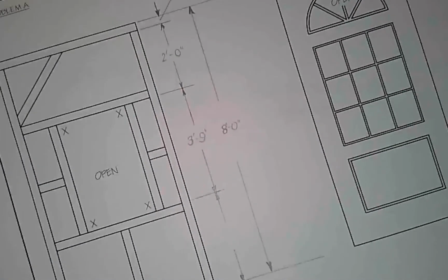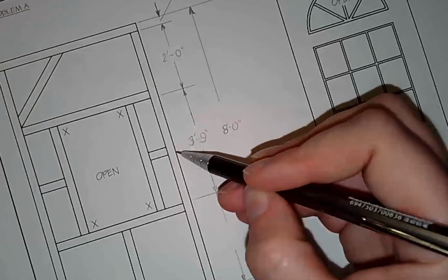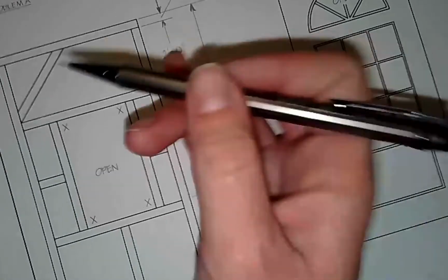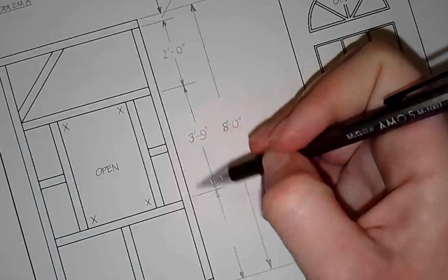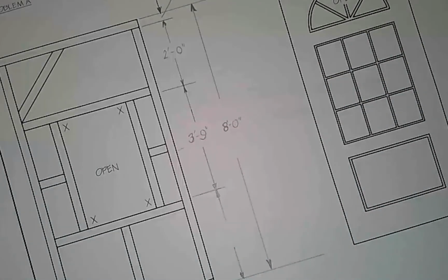So it looks something like that. If I wanted to do an additional row of dimensions, like if I wanted to mark this distance, for example, then I might pull this out a little further in order to put an inside line here. What this is doing is preventing my extension lines from intersecting or crisscrossing over my dimension lines, okay?